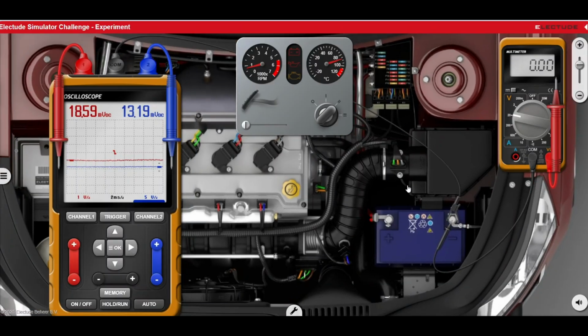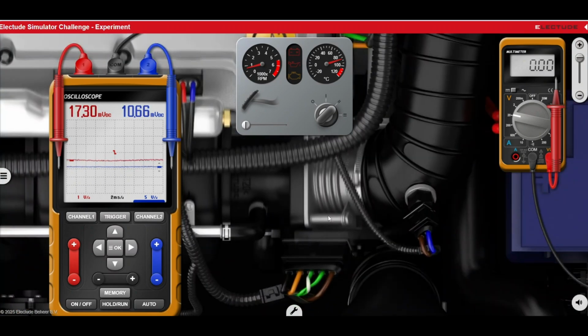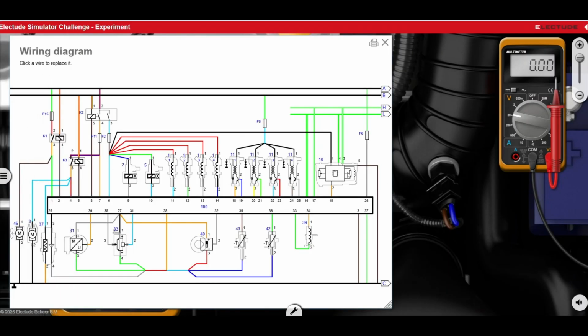Let's go to the throttle control valve or module. If you bring out the wiring diagram, the throttle valve control module is actually a module with the valve. It's a valve with the module inbuilt. You see that it has 1, 2, 3, 4, 5 wires. One wire, this one, is for the power. Must have 12 volts on pin 1.